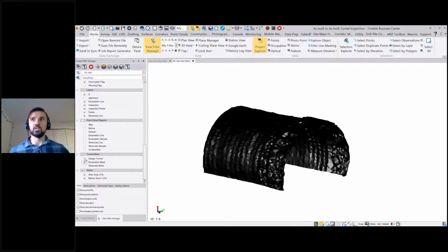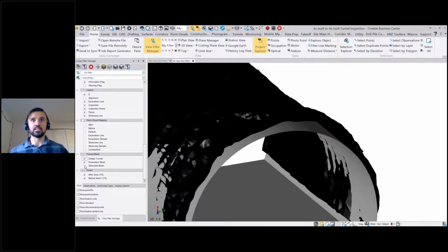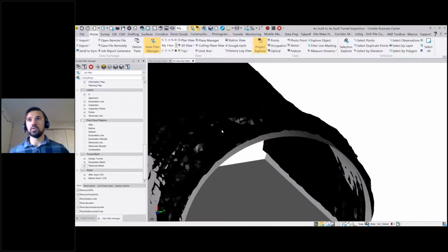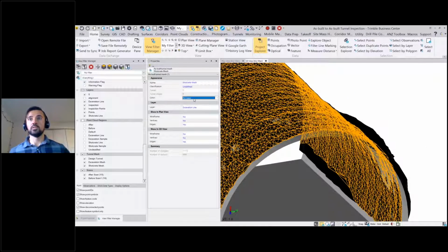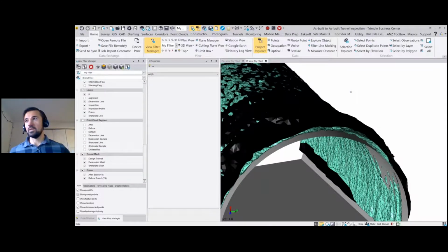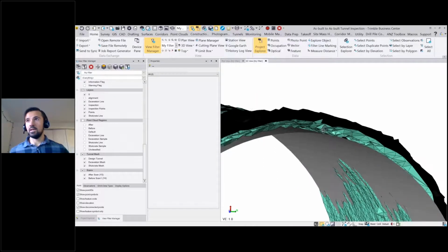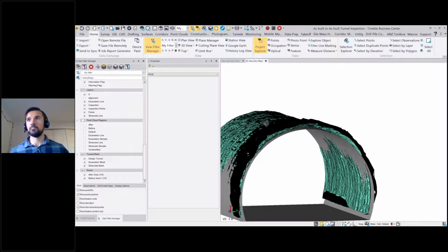But along with those meshes, I also have the design shape, so we can see all of that in context. If I turn on all three, maybe I'll change the color of the shotcrete so it's easier to see. Let's change it to, I don't know, what's a good color? Change it to aquamarine. Now I can see in context those three different layers, right? I've got a design, I've got an excavation, and I've got a shotcrete, and how those all look in 3D.